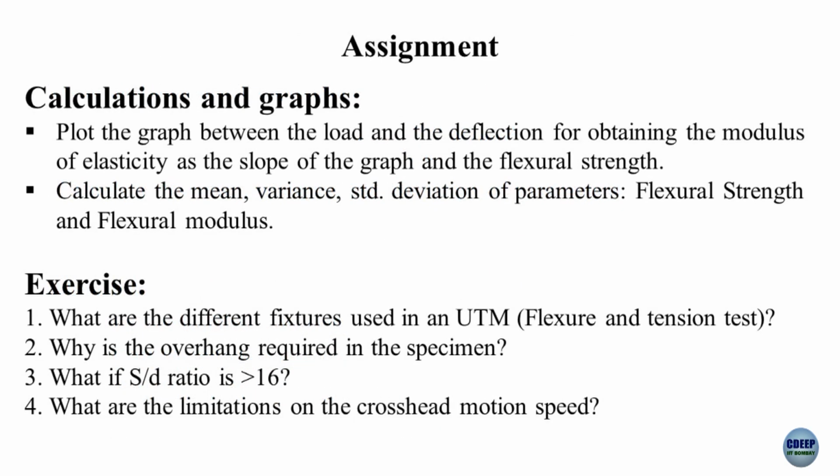The assignment for the flexure test is that you have to plot the graph between load and deflection, in order to obtain the modulus of elasticity from the slope of the graph, and the flexural strength. Then we will be providing you 5 to 6 samples of GFRP so that you can calculate the mean, variance and standard deviation of the parameters, that is the flexural strength and modulus. And the exercises are given in your lab manual.